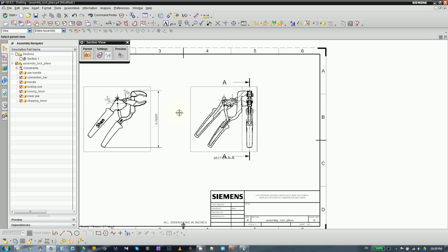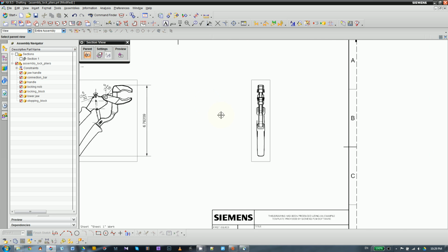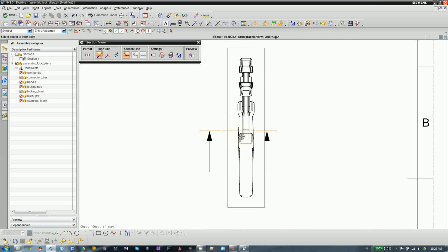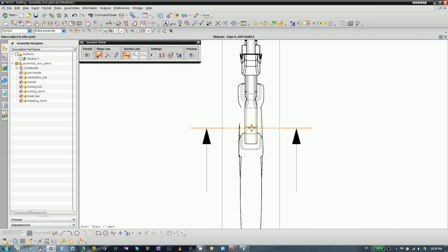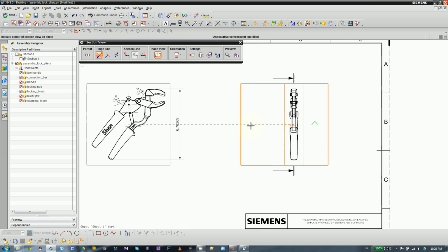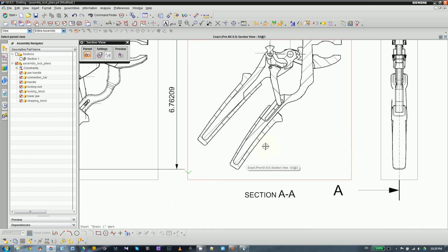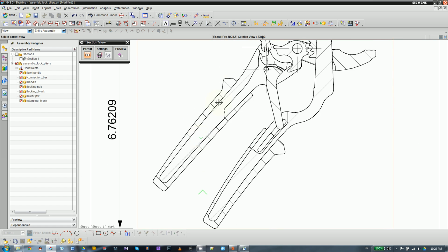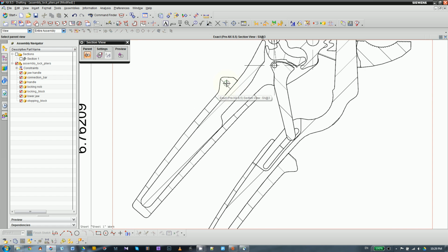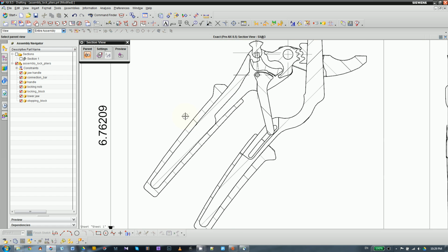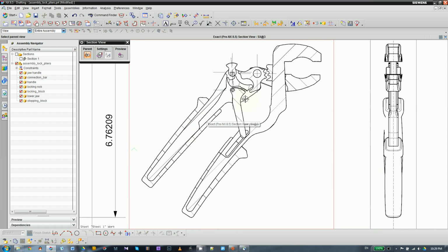So there we go, and that's not very good. Okay, cutting plane, click the point, and you can drag to the position you want. That's the cross section. And bear in mind that I have the boundary line here because I didn't unite those swept to the extrude. You might not have those boundary lines here.